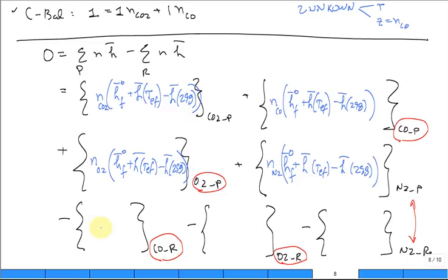And then down here for the carbon, so what is the amount of the carbon monoxide coming in? Wasn't that N of 1? So let's put that one in right away. It's the number. Okay, fine. Put the number of moles of carbon monoxide in the reactants coming in times the enthalpy of formation plus the change in H. Well, this is delta H bar for carbon monoxide, it comes in at 298. It comes in at standard conditions, so the delta H is 0.